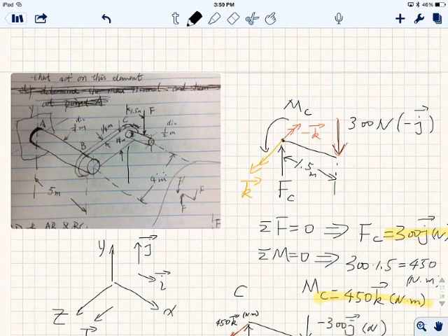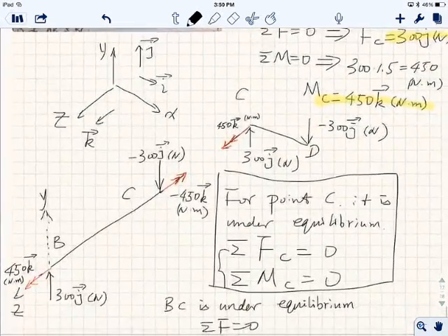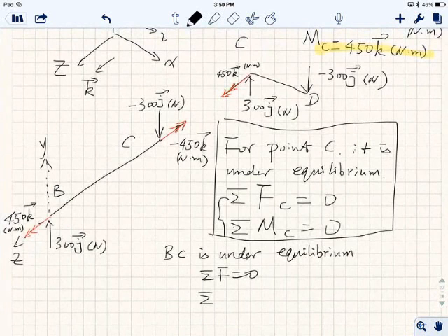If you look at this picture over here, you can also understand. See, when you have a fixed end at point C and everything is fixed, F is probably going to cause this CD to go down, right? But at the same time, it's going to twist the BC, right? Because imagine if you apply a force over here, BC is going to be twisted, while this CD over here is going to bend down, right? So that totally makes sense by doing the force analysis here. So 90 degrees bending, 0 degrees torque, okay?